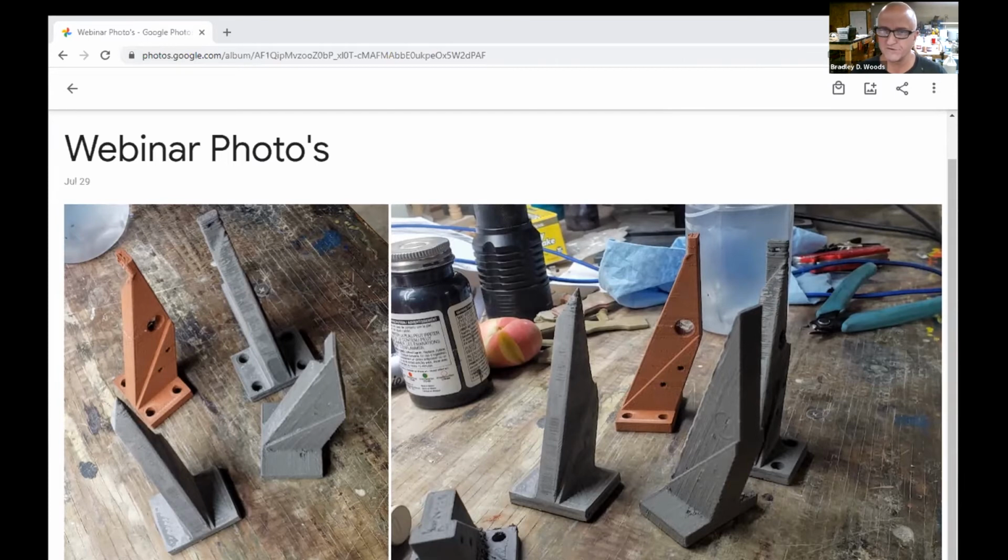So at the end, the user will just drill a few holes in it for precision. Considering near net shape is important. If you've got some tight tolerances that you need to meet, this process should be considered near net shape. Drilling the holes after the fact is a perfect solution for making sure that your holes are exactly the right size. And that goes the same for tapping threads. Threads may not center the way that you like them to, so tapping those threads post sintering is the way to get those exactly right.